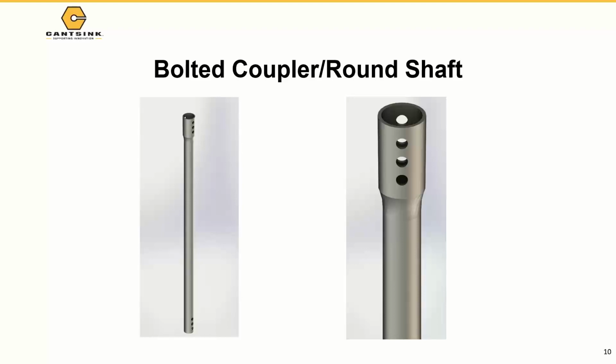You will see the torque correlation factor KT for that helical pile shaft, because these are tested, and we find out this KT value. That's why they have them in the ICC-ES report. That's because AC358 requires that you do field testing, tension and compression, to find the torque correlation factor KT for that product. For instance, the 2 7/8-inch outside diameter shaft has a KT value of 9. But when you go to the ICC-ES website, not everybody has a KT value of 9.